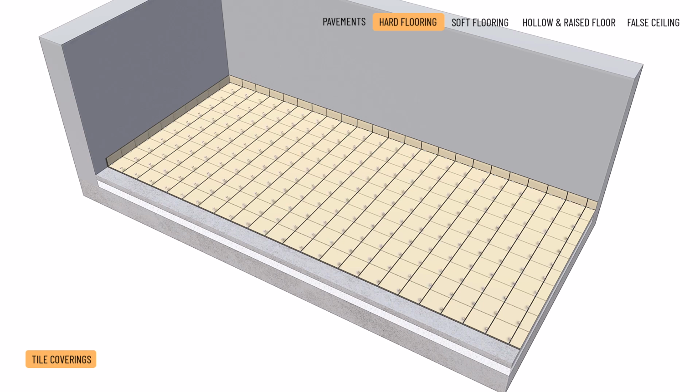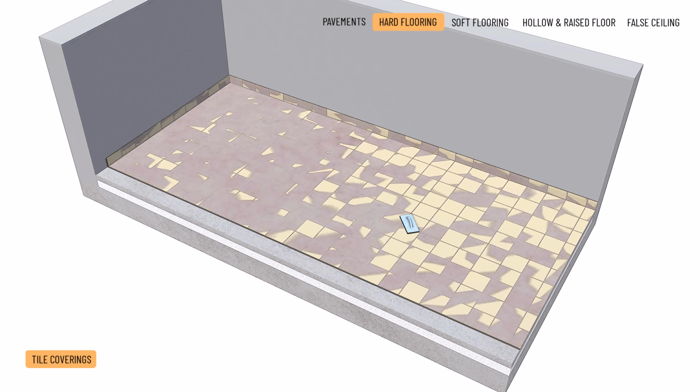The spacers are removed and the grout joints are moistened. Pre-coloured grout is mixed with water on site and spread over a section of the surface and pressed into the joints using a grout float. The filled joints are compacted with a damp joint smoothing tool. Gradually processing, joints should be filled across the entire surface.